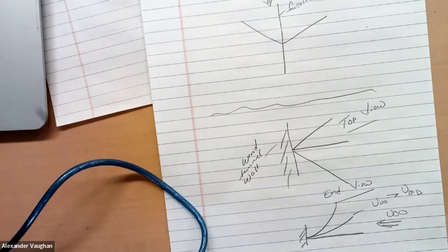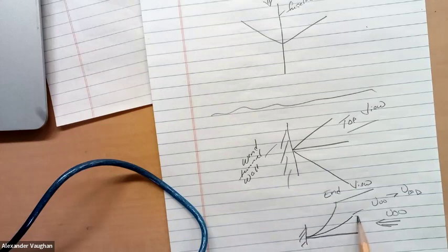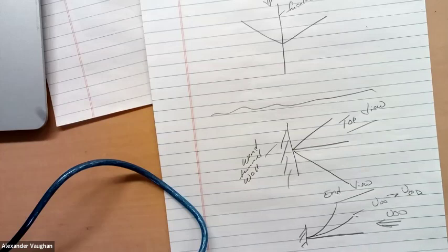So if I have a cantilevered beam like this, there's actually a nonlinear stiffness when I get to larger and larger deflections, and that governs the shape. The shape can be predicted by a linear model, but the actual absolute amplitude, I would have to use a nonlinear model.